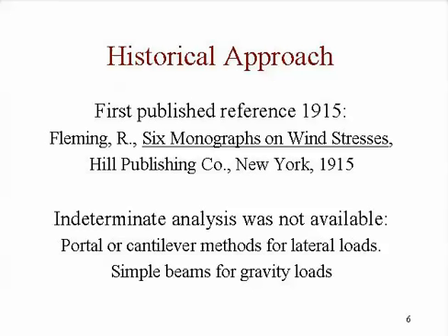Back then, of course, we didn't have our computers. We didn't even have moment distribution. And so indeterminate analysis, what you were going to do if you had a moment frame, for instance, relied on the portal method or the cantilever method. And it relied on just simple beam design for gravity loads. And that's the start of an approach that became known as Type 2 with wind.